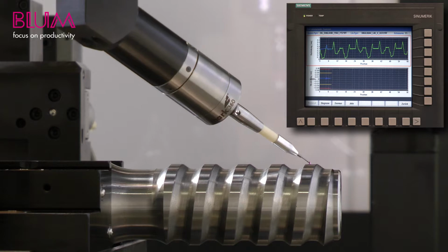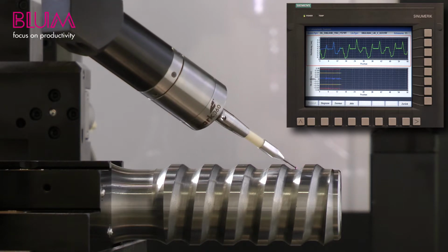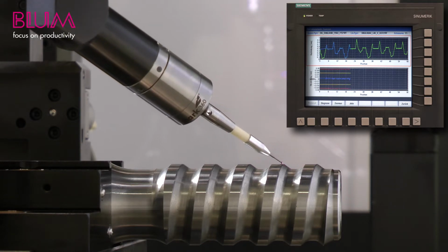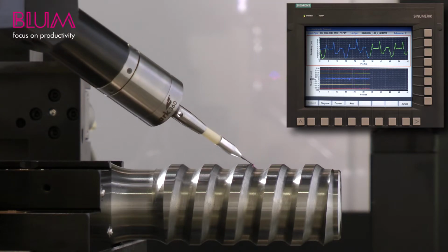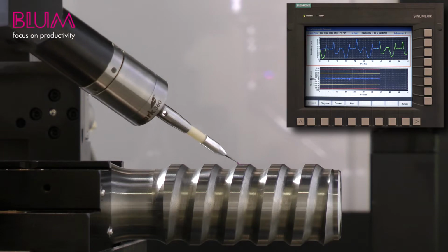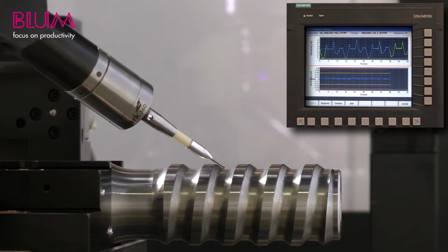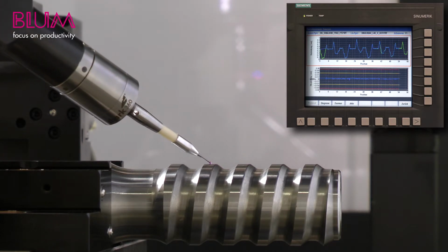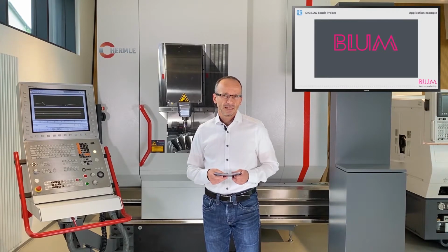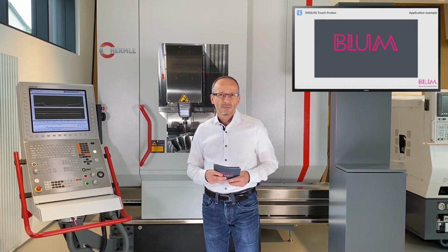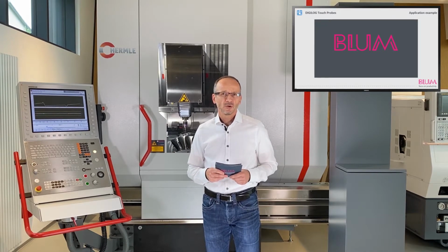Before the start of mass production, a master scan is generated once on a good part to record the target state of the profile. A feed rate of 200 mm per minute was selected for this specific case. You can see a relatively short stylus with a ceramic shaft and a very small ball. With regard to the stylus insert, there are no design restrictions in terms of material, length or probe ball. The design is optimally adapted to the respective measurement job.